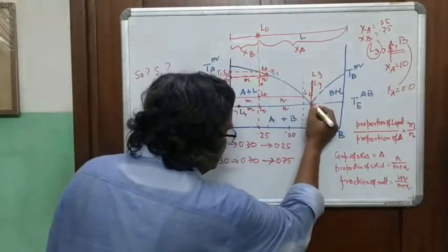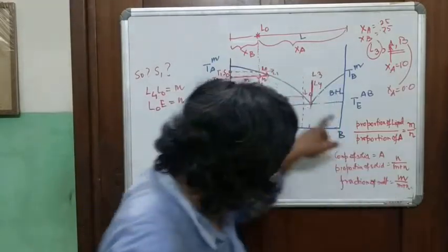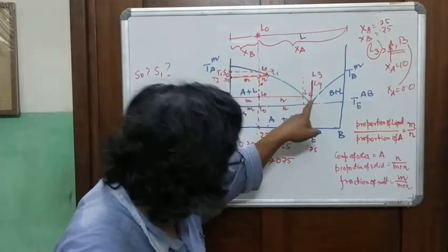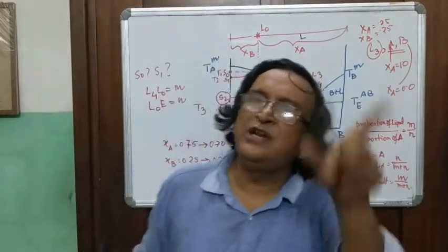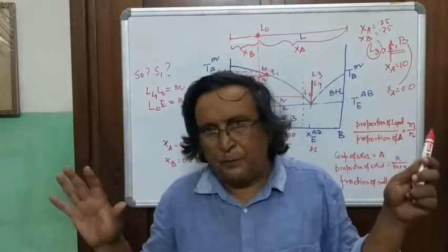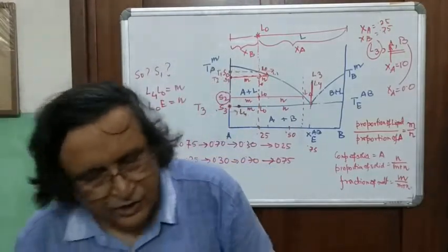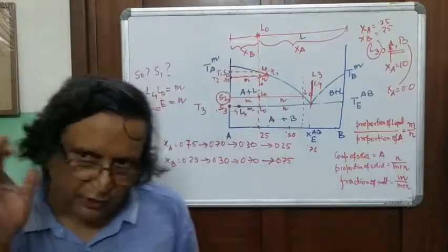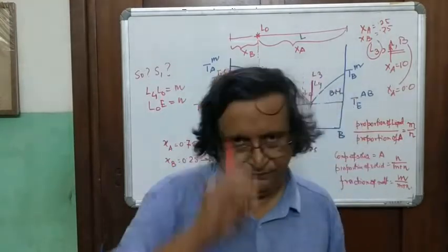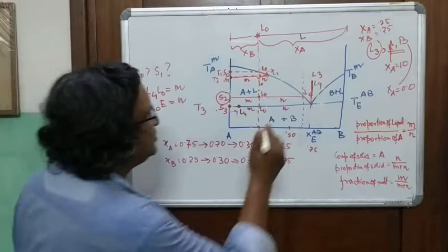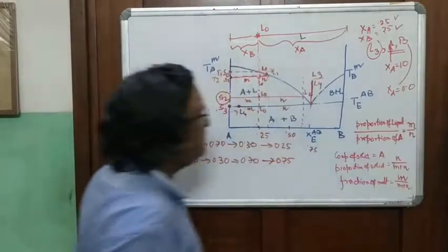When you reach this point, you can't change the temperature anymore, because in this diagram the only point where pure A, pure B, and liquid are in equilibrium is this point. There's no other point where the three phases are in equilibrium. So now whatever you do, your liquid is not going to move away from that crucial point called the eutectic.